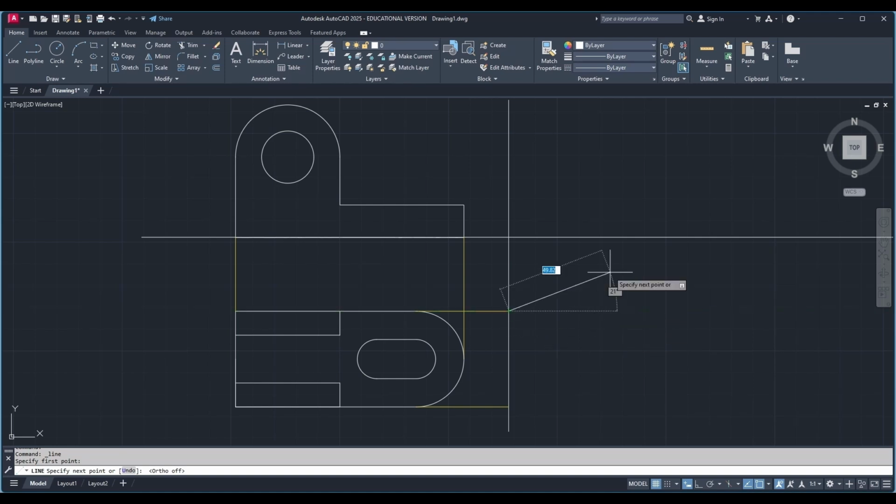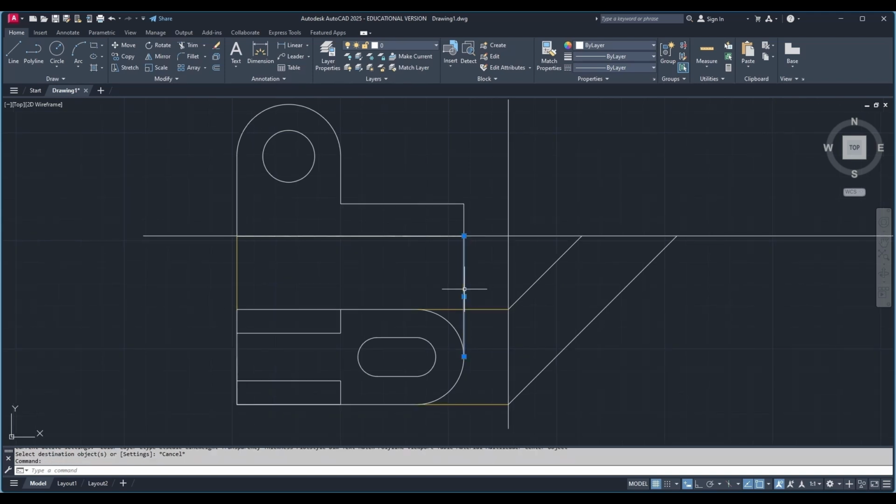I'll draw the 45-degree line to get the dimensions to the side view. So what I will do is I will turn off the ortho, then I will position the line above the XY line, then use the tab option to get to the angle option, then hitting enter. I will use tab so that my dialing is on angle option, then hit 45 and hit enter, like that I'm doing. So I will trim off the lines which are coming above the XY line like this.